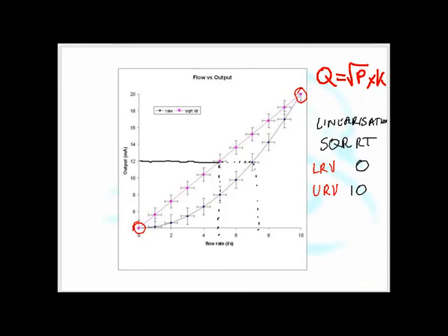So the real flow will actually be more like 7 liters a minute. And it might not be until a couple of years down the line, one of the operators says there's something very wrong with this flow meter, that anybody realizes that the install engineer, instead of selecting square root, selected linear. So that's a little bit of a trap for young players.